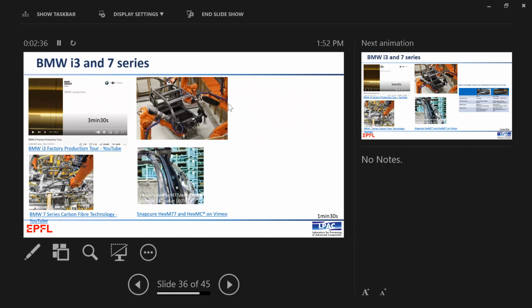The other main application of carbon fiber in the automotive world is in the 7 Series BMW. So here, the way they approached it changed. The i3 was mainly RTM. Here, this is mainly compression molding of prepreg. RTM had more quality issues, higher reject rates, dry spots and lots of trim in the process. You'll see that here. The prepreg is more industrial.